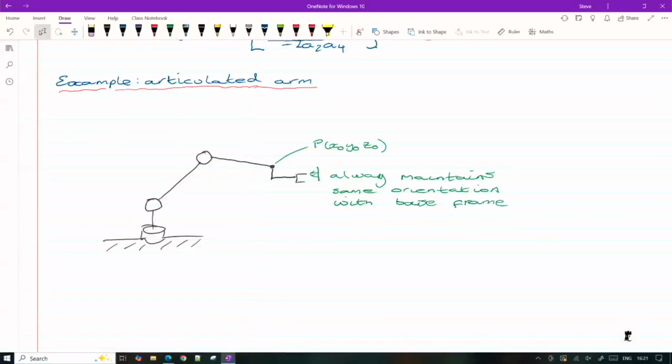Okay, so just remember that as you move the arm around, there's a set of linkages. If you look at the Dobot, that means the end effector will always remain parallel to the ground. And as I mentioned last week, that's kind of what you want if you're moving pallets around. You don't want to tip a pallet at an angle. You want to keep it flat to the ground. And the way that this is configured will naturally do that.